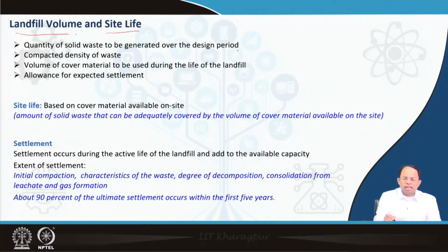So this is determined based on the quantity of solid waste that is generated over the design period of the landfill. Sometimes we can decide the design period based on land area available. Alternatively, if I know that I have to have a landfill which will work for so many years, then we have to determine a land area or proper site where we have the adequate land area. So in any case we have to estimate the total landfill volume and the area required for it.